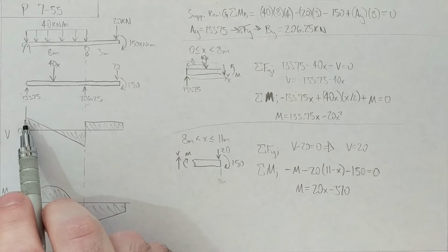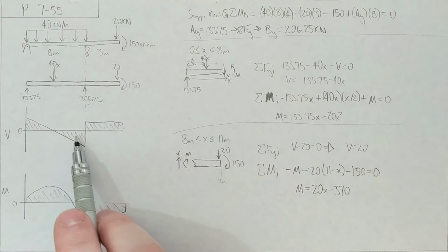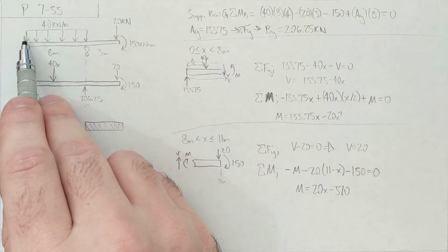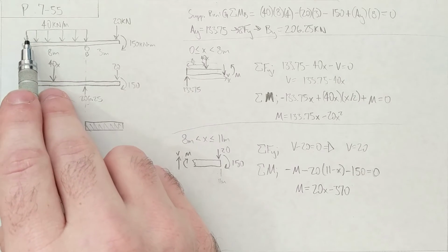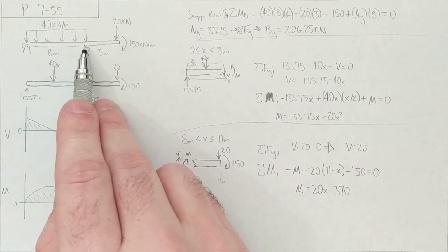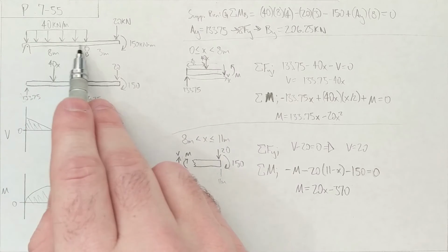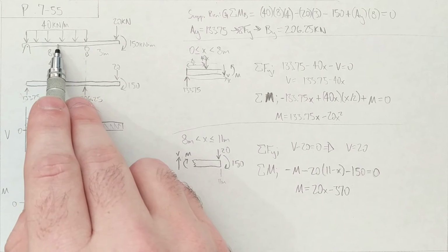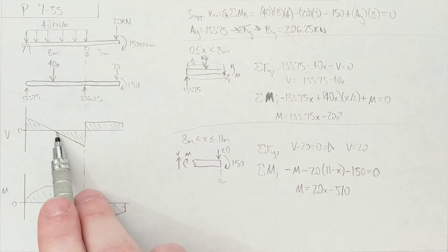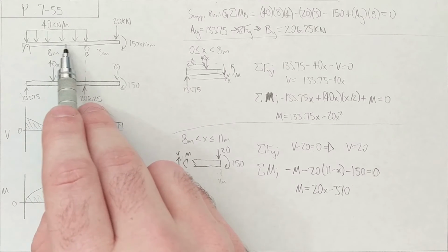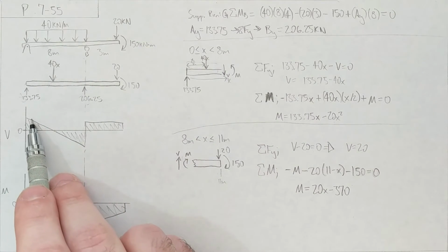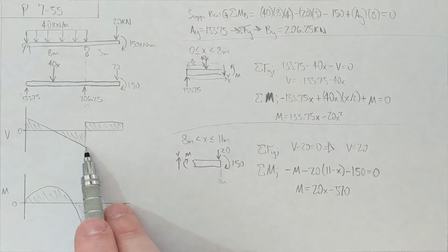All right, so this is what you end up with when you have a uniformly distributed load, right? You have this shearing that starts out at this full positive shear, trying to turn it clockwise, and then it's trying to turn it less and less clockwise until you get to halfway between the two supports. This is for when you're supported on either end of a uniform load. And then you start getting this negative part whenever this starts trying to turn things counterclockwise. So it's just this nice continuous gradation from there, okay?